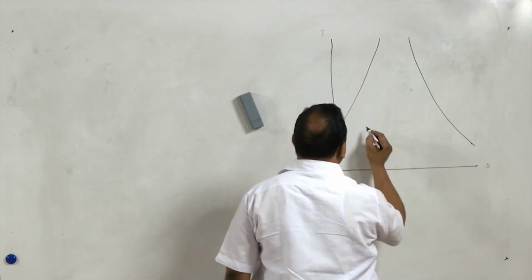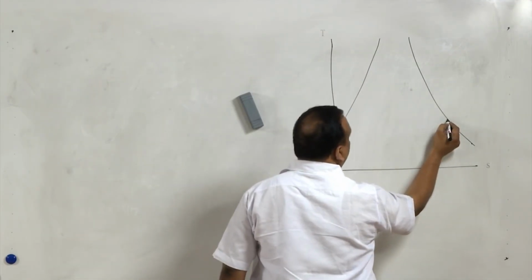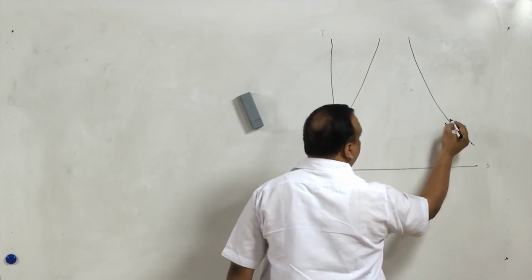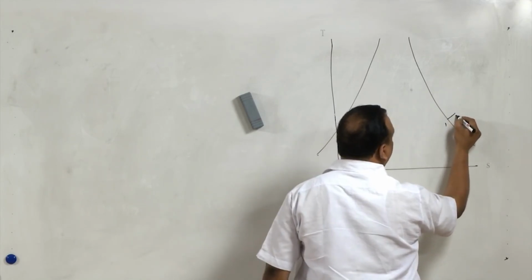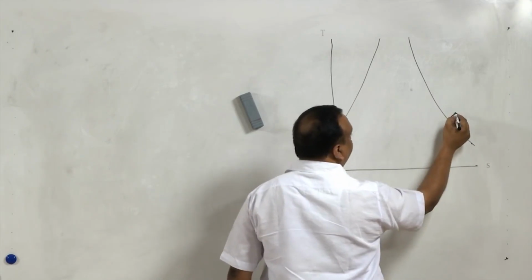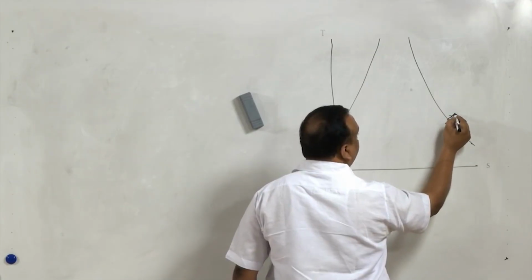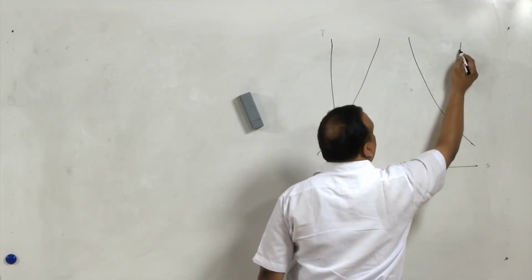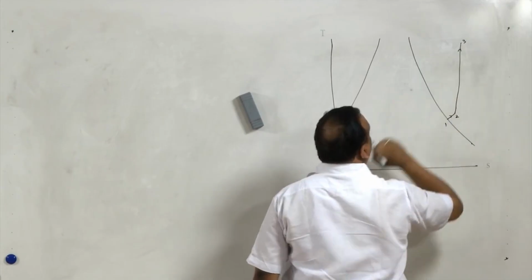Temperature entropy diagram. The vapor coming from the evaporator is superheated by 5 degrees centigrade. So, state 1 is the saturation state, state 2 is the superheated state. Then the vapor is compressed in a compressor, state 2 to state 3.